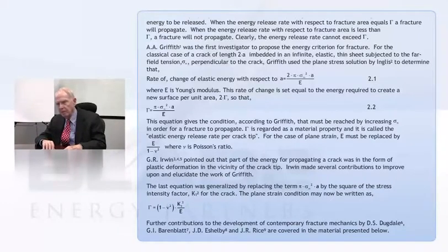One of the things he did is he related this property, gamma, to a property that comes from purely elastic analysis. So far, all we're talking about is cracks in brittle material, and therefore one would think they could get away with an analysis, an elasticity type analysis.